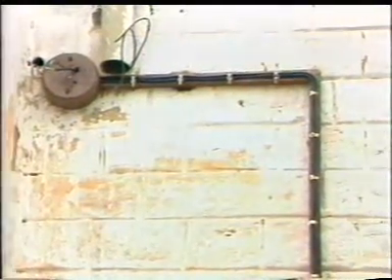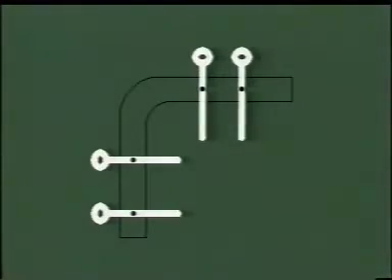Battens should be secured to the walls and ceiling with the help of wooden gutties. Rowel plugs are preferred over gutties nowadays. Link clips should be fixed at an interval of 10 cm in case of horizontal run and 15 cm in case of vertical run. Smooth curve should be given at the turning point. The distance between gutties should not exceed 75 centimeters.